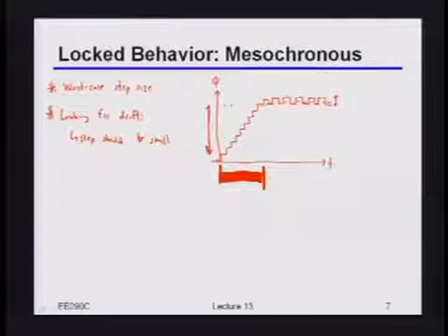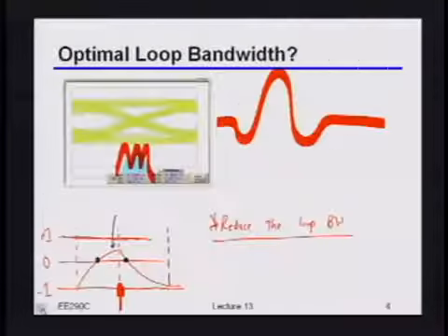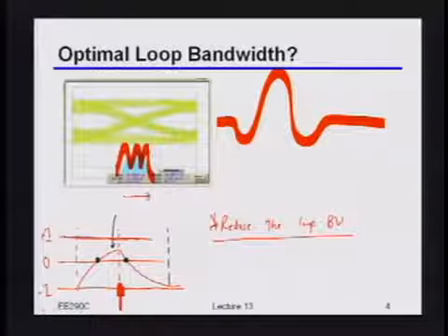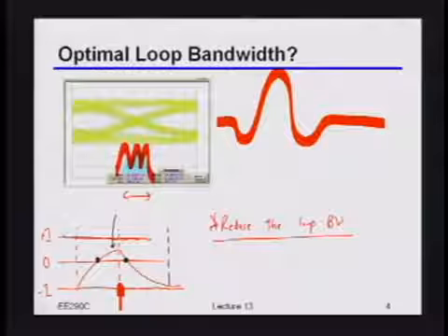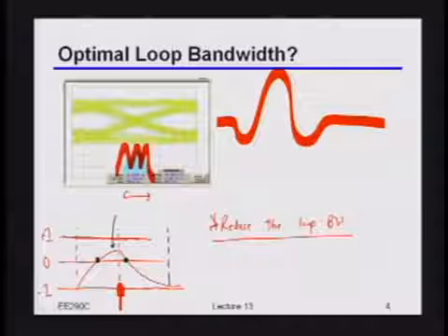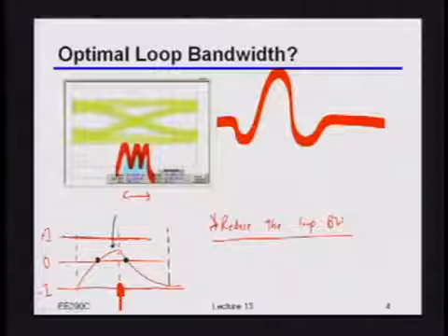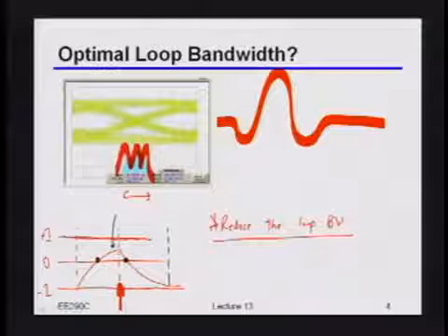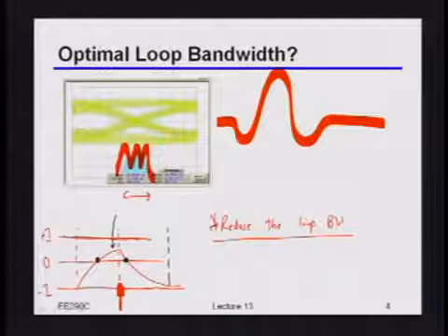And remember we said that, in terms of the CDR, I really don't want to be having anything with very high bandwidth because no matter what I do, I can't really get things right in terms of the data jitter. So my best bet is to try and filter it out as much as I can, to the extent of at least the things that are caused by SI, and then only track the really slowly varying components where everything has been statically shifted, right?